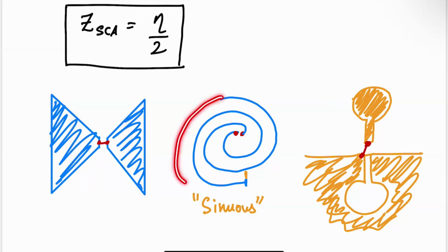In the same way, it's the length of these arms that you make. And in this case, you truncate this sheet at some point. So you eventually have kind of a band limited structure, but they can be very broadband. So you can get like several octaves of bandwidth out of these guys. Okay. There are other ways to analyze bow tie and spiral and so on, but this is one way to look at them.